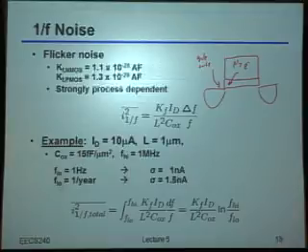Okay? And by the way, it's called a trap exactly because it traps charge, meaning electrons or holes or whatever get stuck in that particular region. So if you all of a sudden have an electron that jumps into the oxide and gets stuck there, how does that affect the transistor from the parameters that we typically think about? What does that do to it?